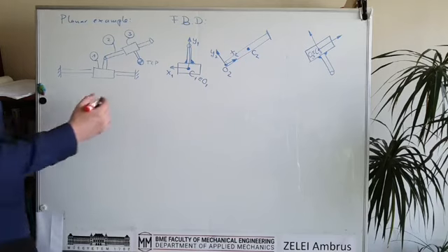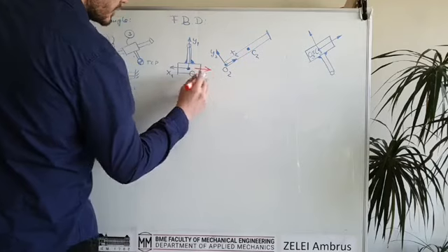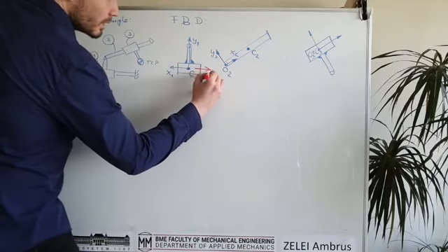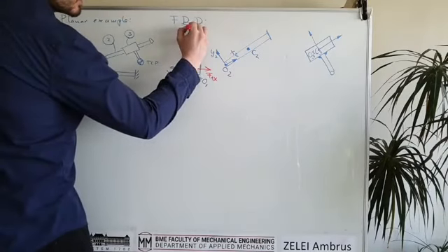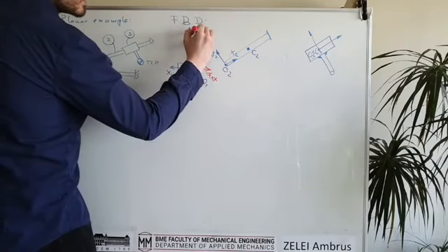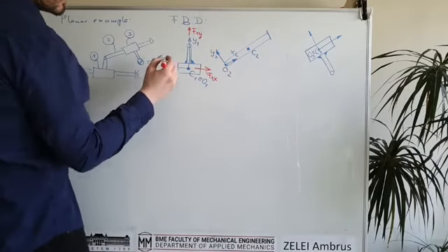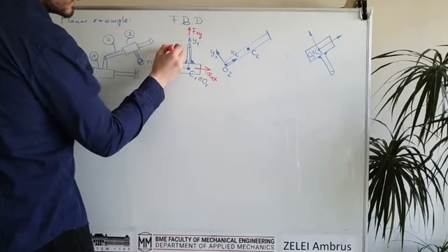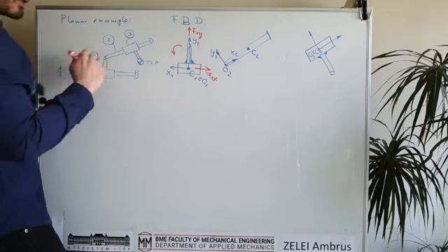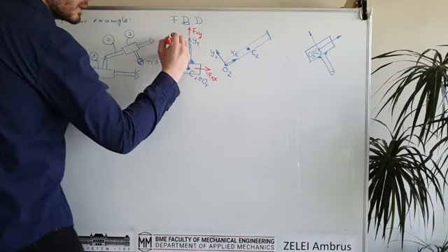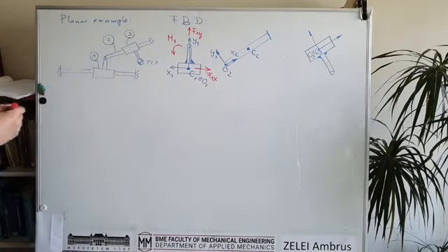So let's take the first drawing. Here there is the joint force which acts in horizontal direction and also in vertical direction. And also there is an unknown joint torque which is describing the action and reaction torque between the zeroth link and the first one. So this is M1 torque.